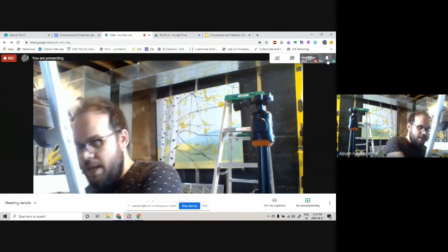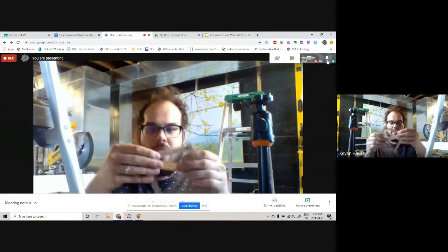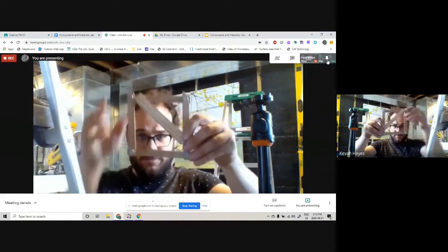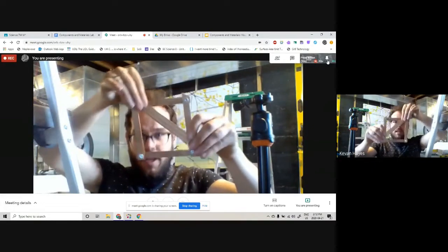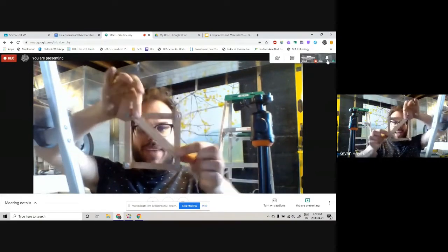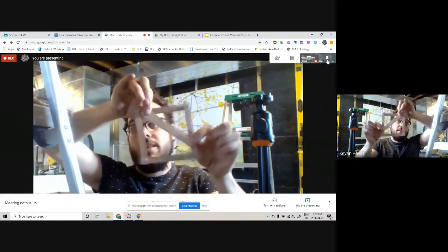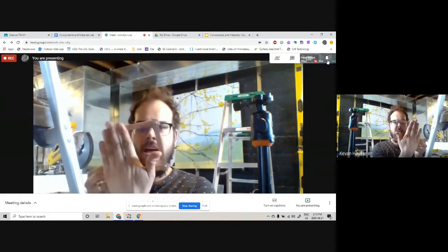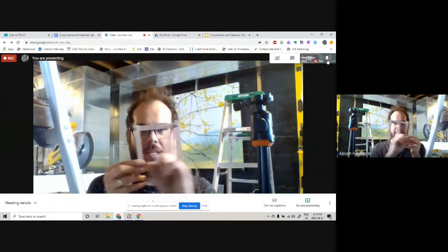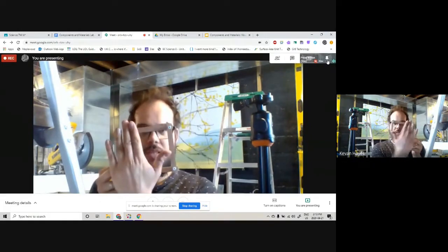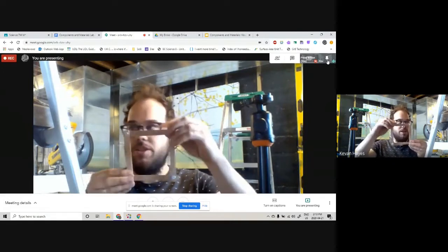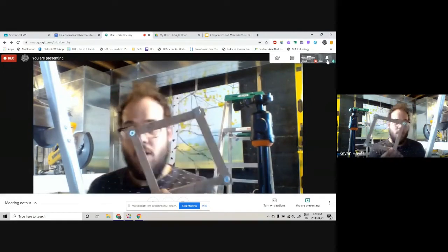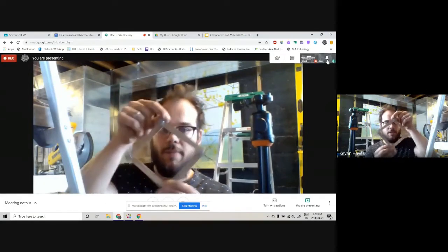Sometimes what you could do is create what's called cross bracing. That's where you add a triangle to the shape. And now if you try to move the top and bottom relative to each other, you can't, because this triangle holds this in place. Another way you might reinforce this shape is to take a layer of cardboard or some planar surface and put it right across this thing, and then it'll be less likely to shear as well. But on its own, it's not very strong because the joints are able to move.